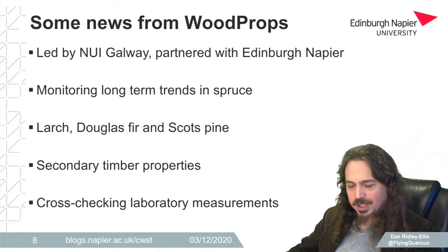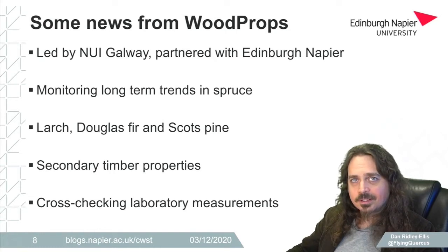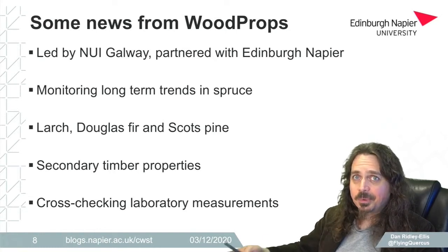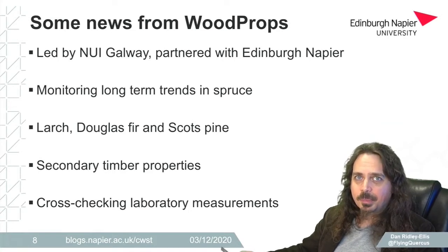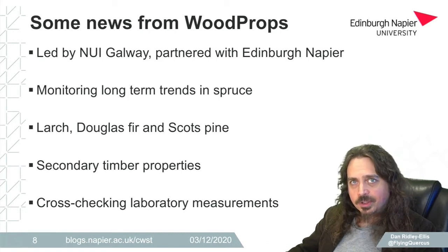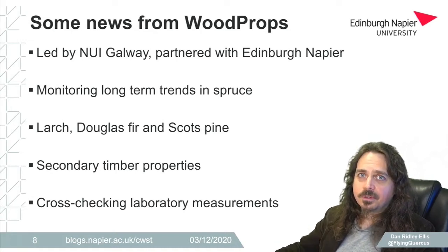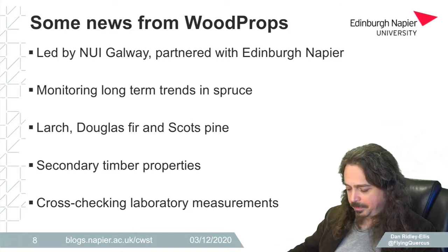And as I mentioned, they've been looking at larch and Douglas fir measurements, and their work has compared with our work and been able to get the grading settings updated and approved for those two species. And they've been looking at Scots pine, and the work that they've done with Scots pine will also go towards potentially new grading approvals for Scots pine.